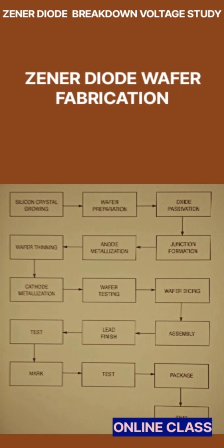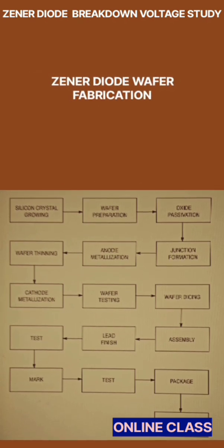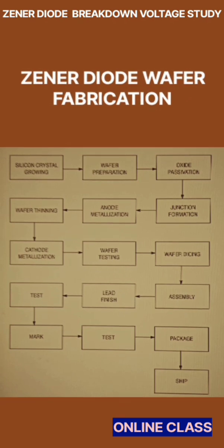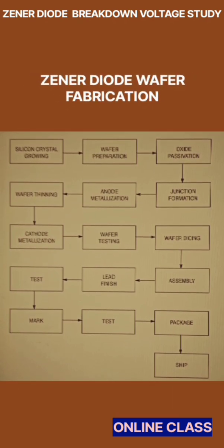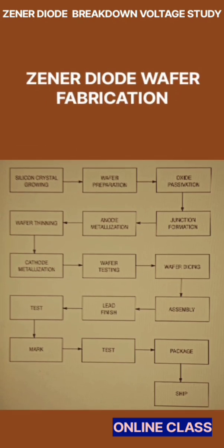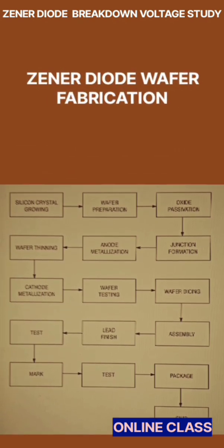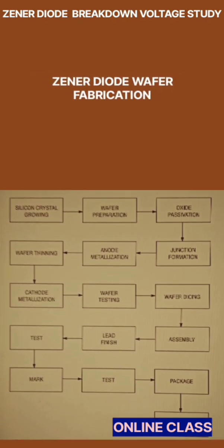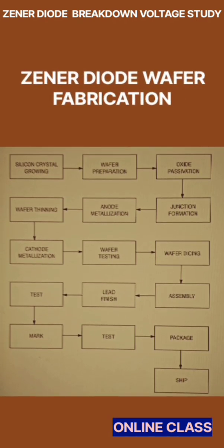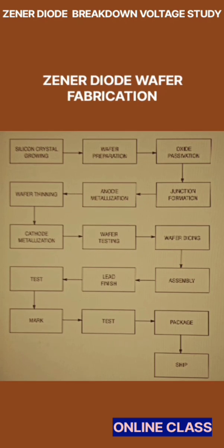Crystals for ON Semiconductor zener diodes are produced using a common technique that starts with ultra-pure polycrystalline silicon. Initially, the polycrystalline silicon is melted in a non-reactive environment at a temperature slightly above its melting point. The precise amount of the desired dopant, such as phosphorus or boron, is then introduced.